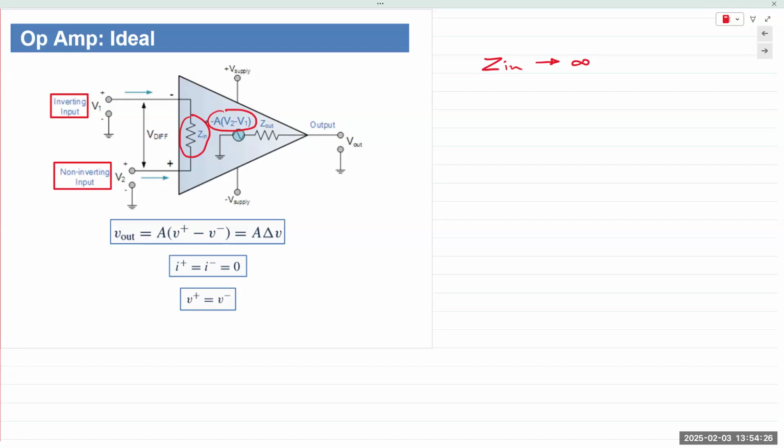If you apply the same signal to the non-inverting terminal, then the output would be amplified but not inverted. That's all it means between inverting and non-inverting. Okay. So the minus sign simply indicates the output is 180 degrees out of phase.